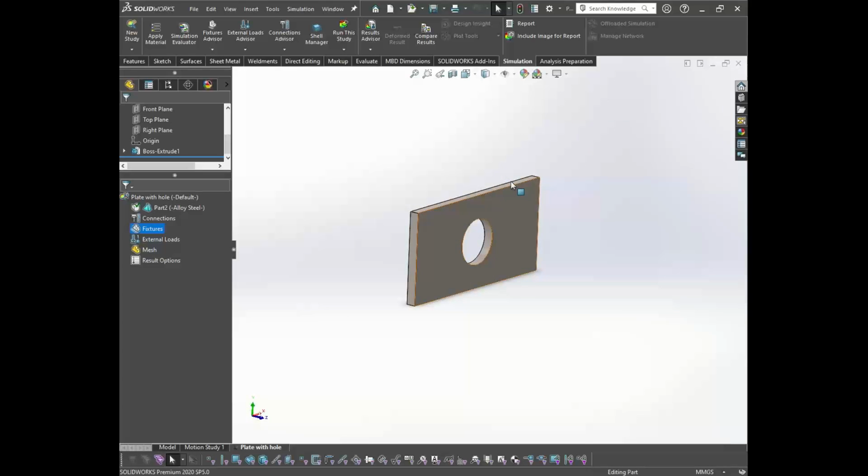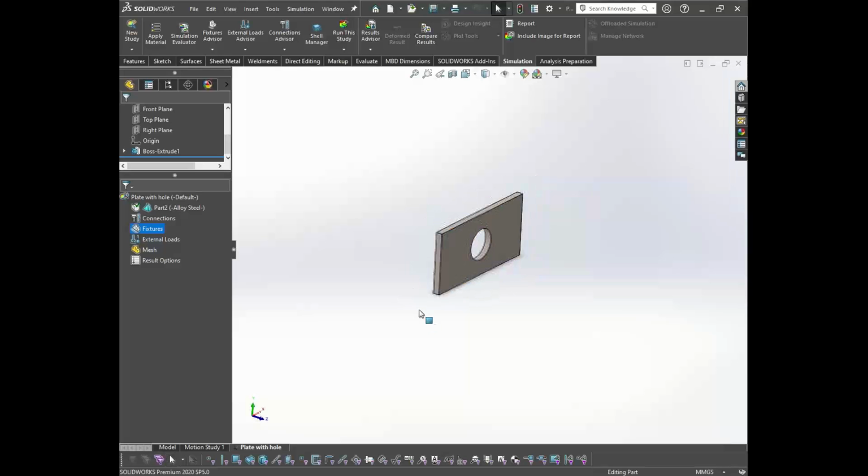Because in the case of strength of materials also, when we find out the stresses or deformation, we get those stress values at the restraining point, right? Suppose we are solving the simple example of, let's say, a cantilever beam. If I am considering the cantilever beam, the maximum stress value I'll be getting is at the fixed end where it is fixed with a wall. So this is how it works.